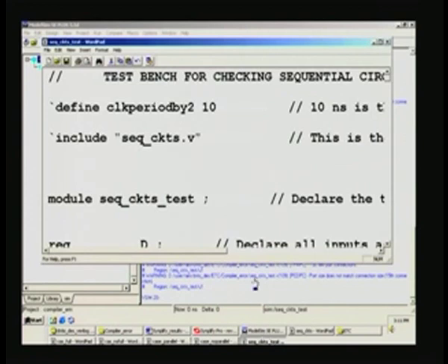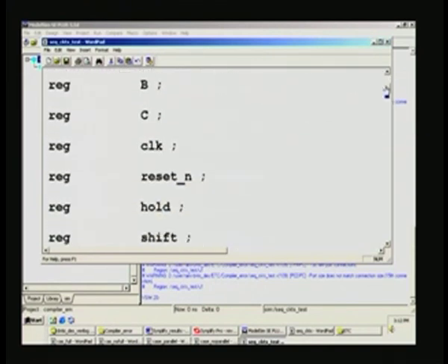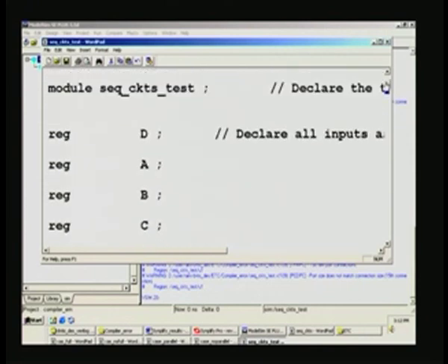And test bench is here, and so we will not repeat what we have already seen, for example define, etc., and module. So, what we will do is, pointing out that inputs or outputs are differently declared. Here it is reg instead of wire normally.